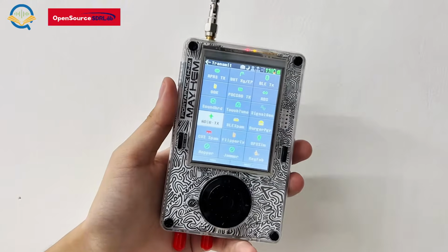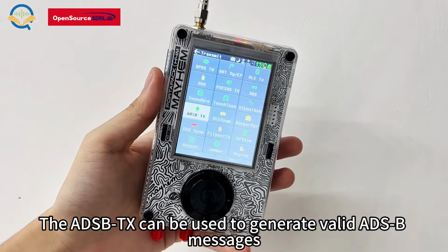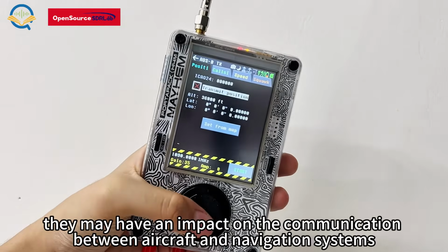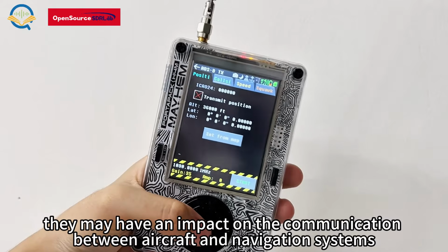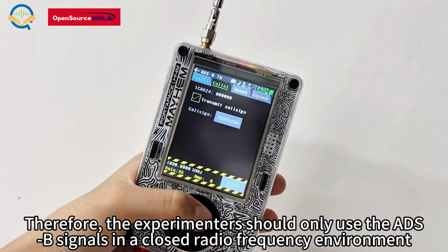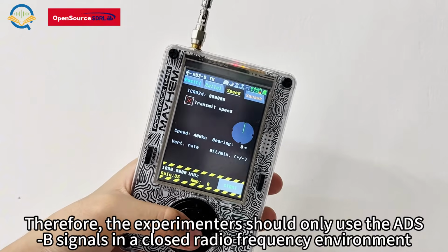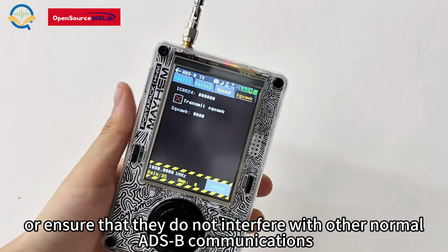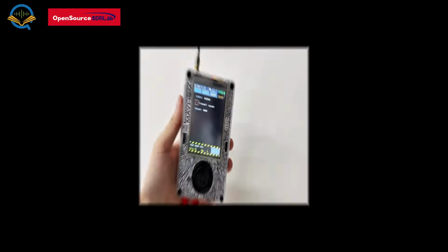ADSBTX. The ADSBTX can be used to generate valid ADSB messages. If these messages are transmitted, they may have an impact on the communication between aircraft and navigation systems. Therefore, the experimenters should only use the ADSB signals in a closed radio frequency environment, or ensure that they do not interfere with other normal ADSB communications.